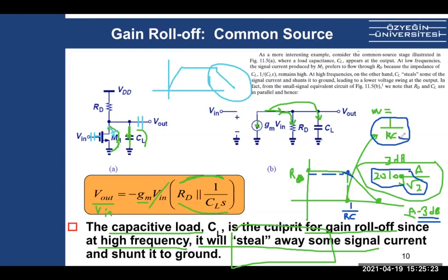Because they are big, that means 1 over RC is small, then it defines small poles. And these parasitic capacitances are so small that 1 over RC is big. There is a parasitic gap between these two nodes, and there is a parasitic gap between these here. Okay, so the brown ones are the caps we don't actually see, but they are there.